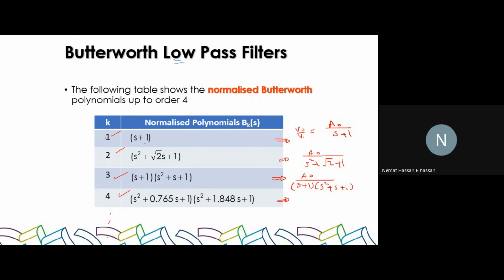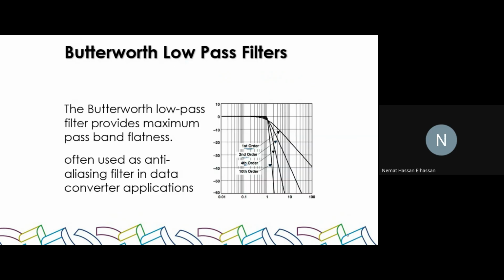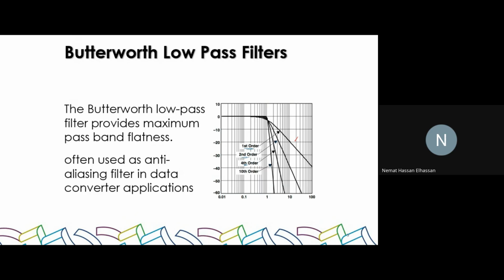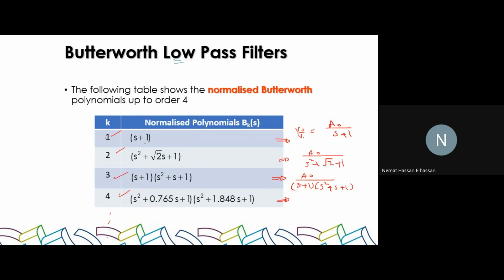So you start with the frequency response. And then you decide that, well, I'm not very concerned with the transition. I just want it to be flat. So I'm going to go for first order. Okay, then design a filter that has this first order equation. If I want it to be second or third, you choose the shape. And then from the shape, you already have pre-existing formulas for output divided by input.